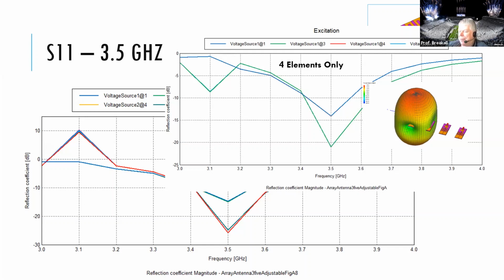It does happen sometimes in arrays. It seems like the spacing though should be wide enough here. That's usually with real close spacing, but I agree that plus 10 dB reflection coefficient, it'd be interesting to see what the impedances actually were, if you had a negative real impedance there.